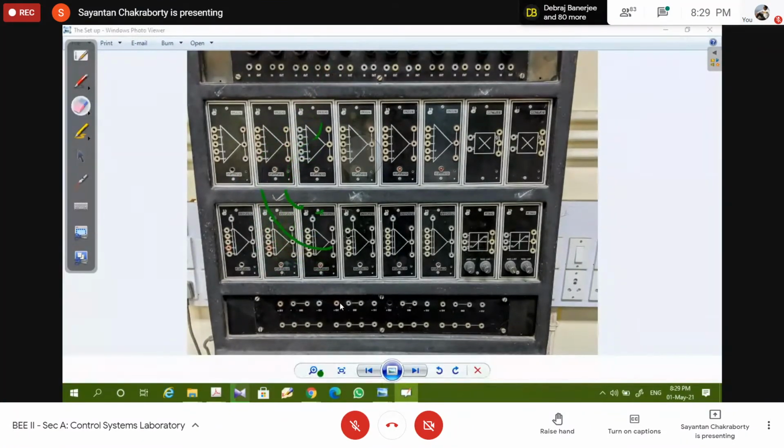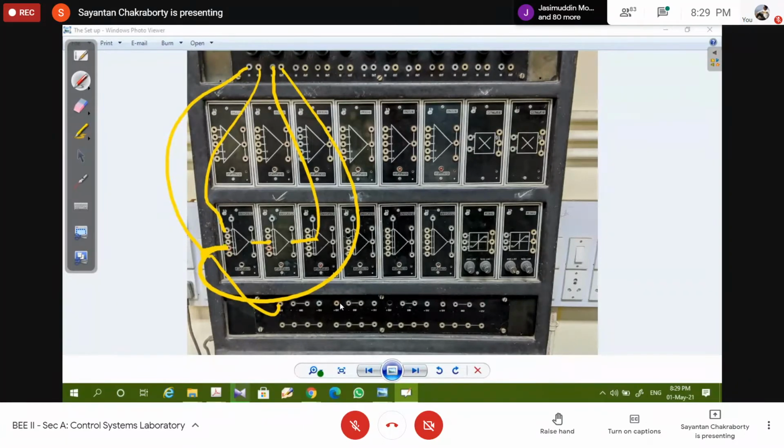This, I think this will do. So first, connect your plus 10 volt to this port, which is set at say 0.98, with the output to this integrator input. From the integrator output, it will be fed back to this, not directly, obviously. This will go to a particular port on that output, and back here.